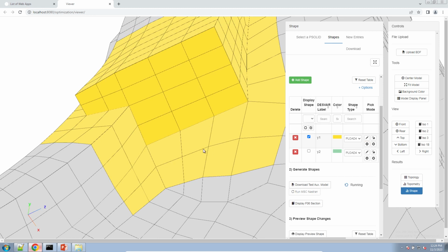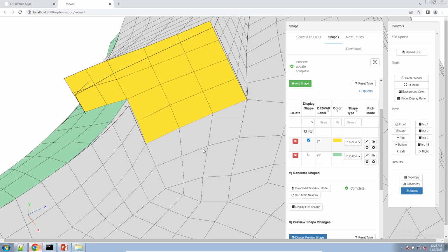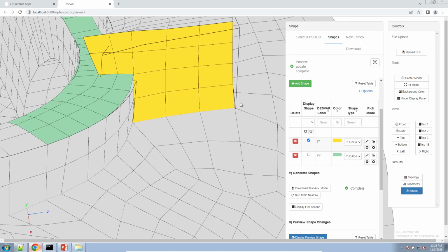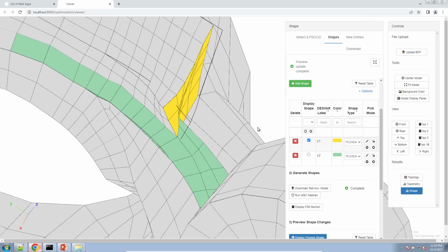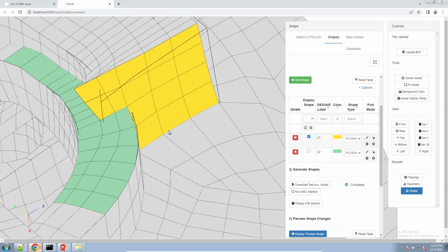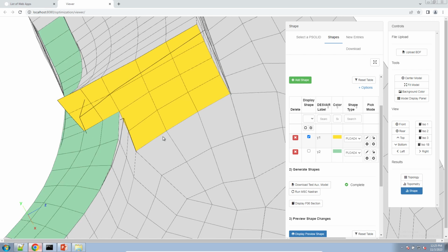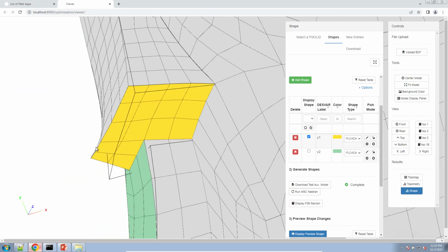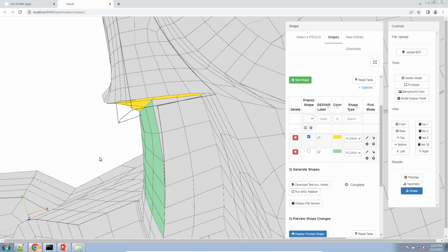And let's look at what this new shape looks like after we introduce elements that can stretch. So you can see that the shape looks better than before. These element faces here are allowed to stretch when this other primary face is allowed to expand or contract. And now, this is where we find sort of the limitation in this way of performing shape optimization.